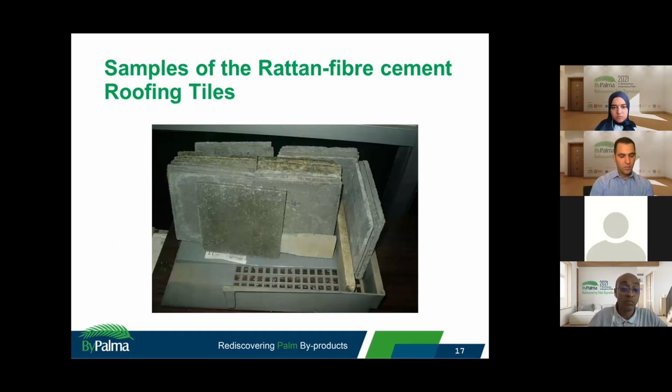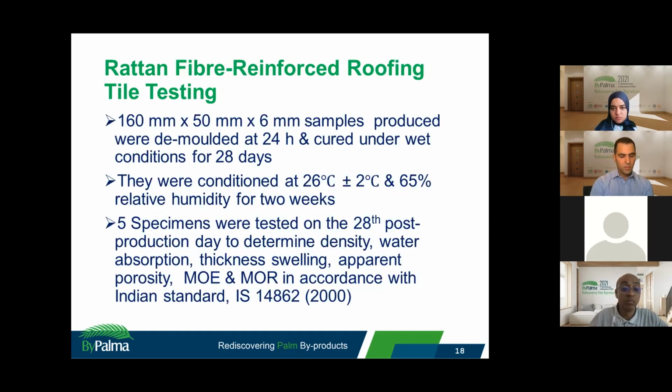We prepared the materials, conditioned them, and tested 5 samples after 28 days of curing. The properties we determined include density, water absorption, thickness swelling, apparent porosity, and modulus of rupture, in accordance with the Indian Standard 14862, published in the year 2000.